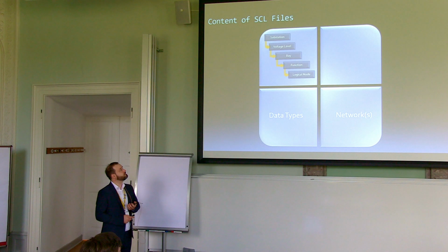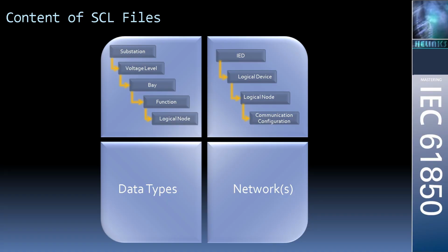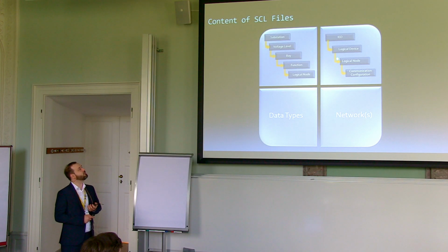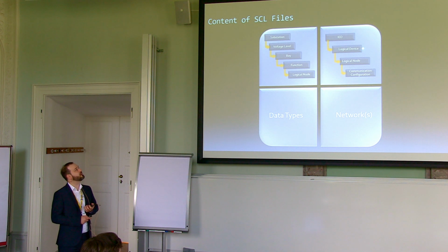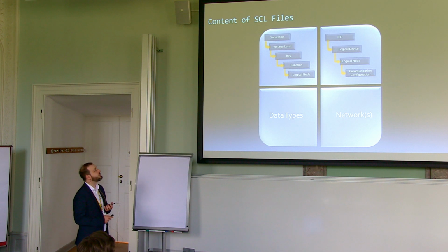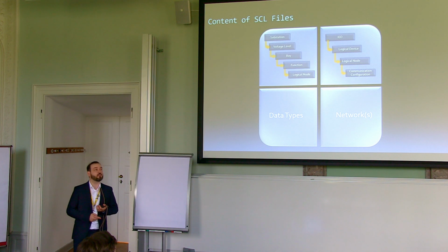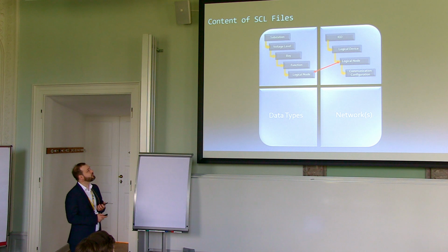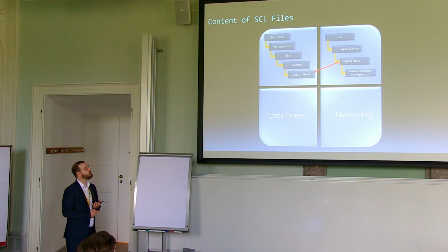In the IED section, we will find IEDs with a very similar layout. We have a grouping of functions, in this case named a logical device, and they also contain logical nodes. Within the logical nodes, we have, for the tools in question, the most important part: the configuration of the communication between the devices. And these logical nodes find their partners in the structural view of the substation.